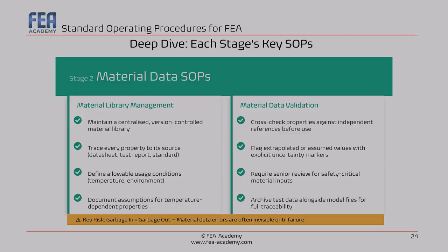You might be under-predicting the stiffness and missing a resonance in a frequency response and modal analysis. You might be over-predicting the strength and missing a failure mode, okay? And you're going to fail a test, definitively. So the fix is very easy.